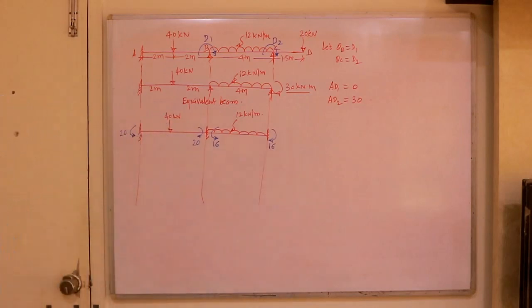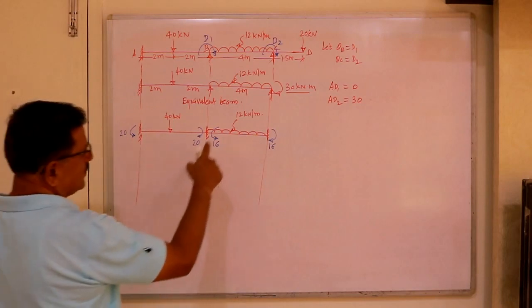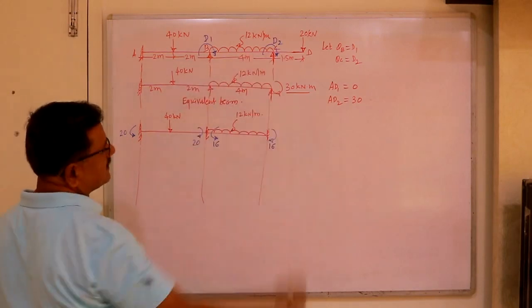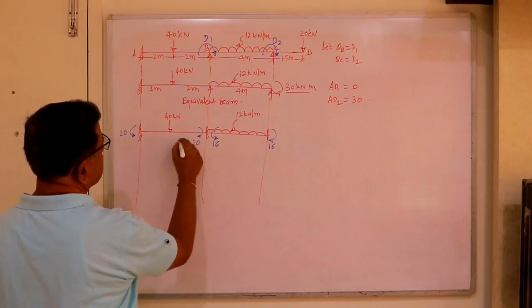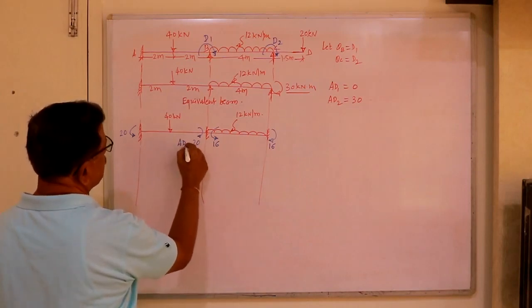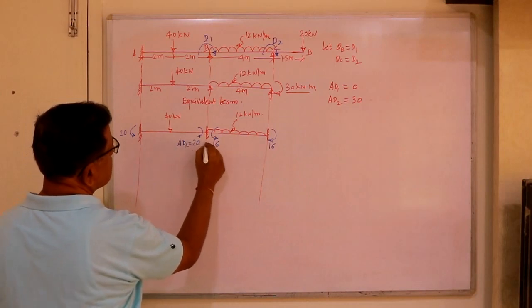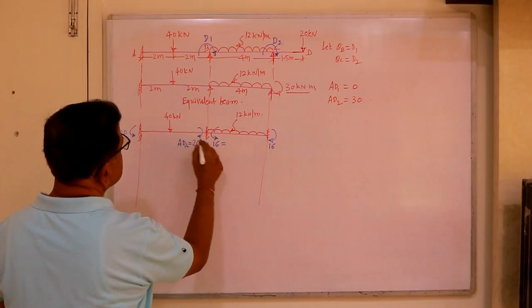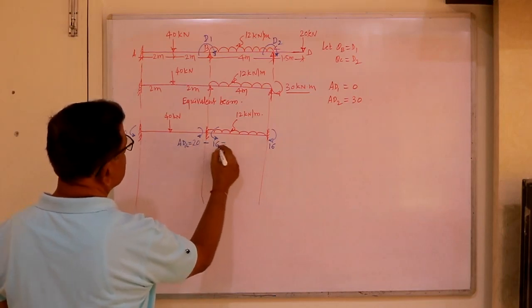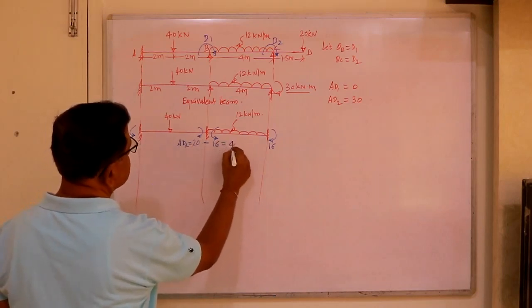Now this is a restrained structure. Now in the direction of first coordinate, no reactions are required because we have unknowns only slopes, so only moments, actions, are required. So this is in the direction of 1 due to loading. This is plus, this is minus, so clockwise is positive, anti-clockwise negative, so this is 4.